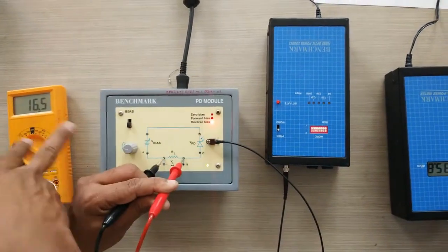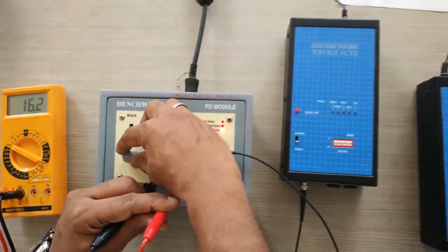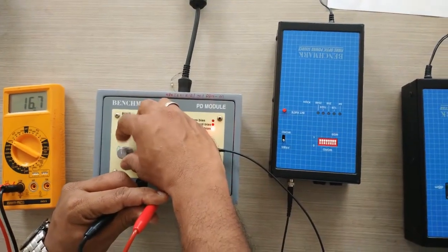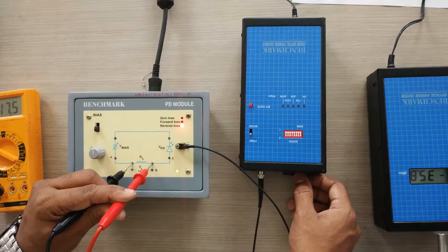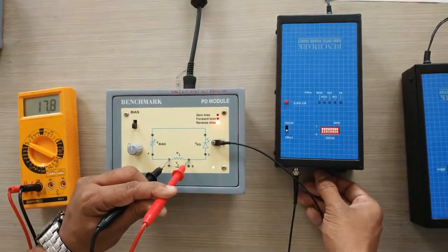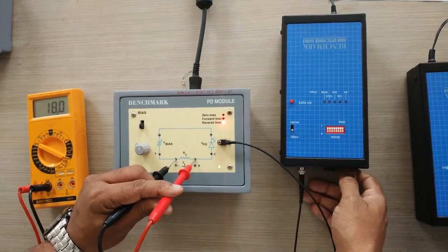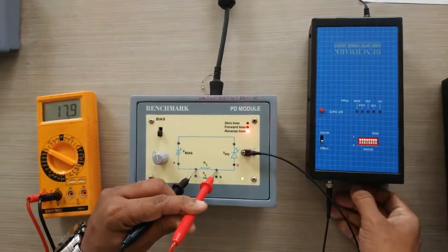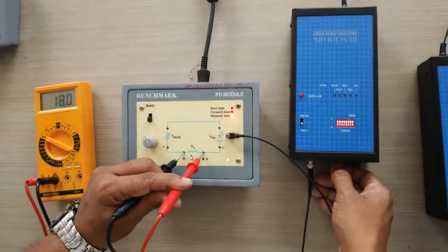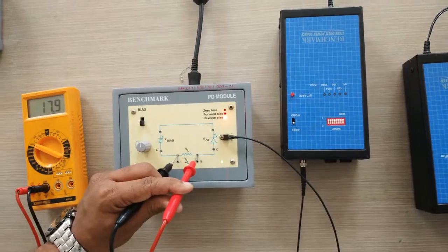So I have switched the bias switch to the reverse bias condition. Okay, so now I have fixed the voltage bias constant first, and I am going to vary the power level. Optical source power level I am going to vary. You could see the voltage differences here, right? It is increasing, right? I'm increasing the power level, and by varying this power value you could plot the power and voltage characteristics of this photo detector in reverse bias.